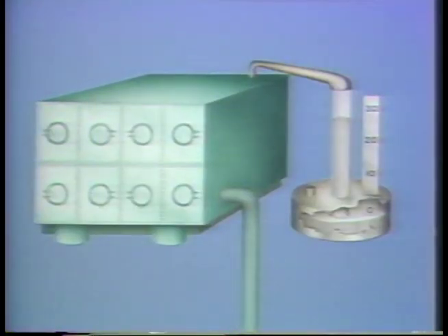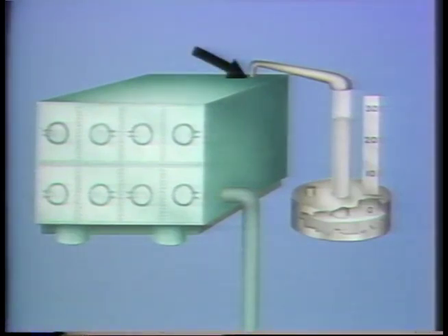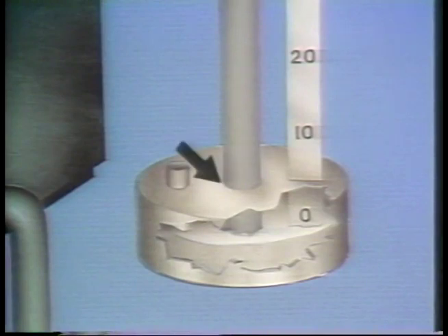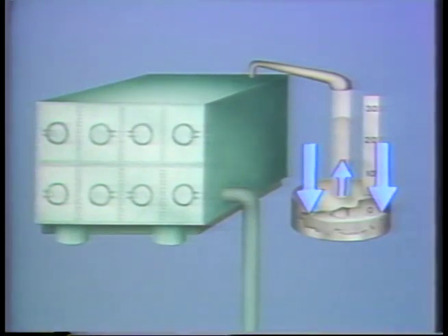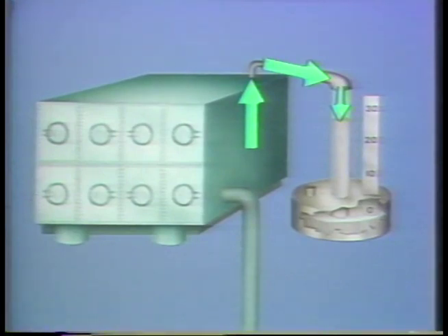Okay, now let's look at the way we measure inches of mercury vacuum. Here's the condenser, and here's the manometer. This manometer looks quite different from the one we just looked at. It's made up of a tube in which the top end is connected to the condenser, and the other end is inserted into a container of mercury. Atmospheric pressure pushes down on the mercury in the container, trying to force it up into the tube. The condenser vacuum pushes at the other end of the tube, trying to push the mercury out of the tube.